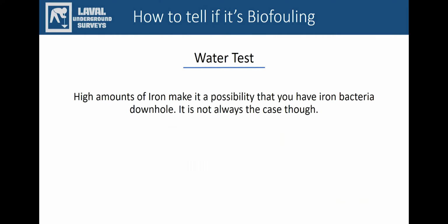A water test can be done to test for iron, but there are more invasive tests for iron bacteria. Normal water tests will tell you that there is iron, but having high iron does not necessarily mean that there's high iron bacteria. It's definitely likely, but it's not for sure. It's always safer to get a specific test for iron bacteria than to assume there are high iron bacteria amounts downhole.